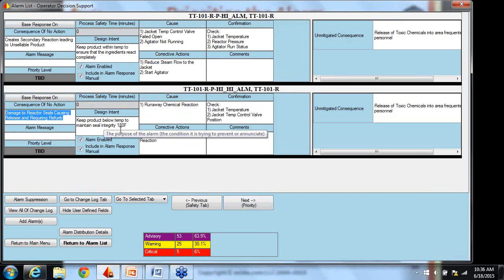And in this case, we thought about what are the situations that we need to prevent. Initially, we had two alarms with their alarm limits close to each other, both related to product quality. Well, as part of our preparation, we found that there was actually a call for an alarm to be a safeguard. So we want to take the high alarm and make it used for the safeguarding action that was called out in the PHA. So we have done the rationalization with that as its purpose.